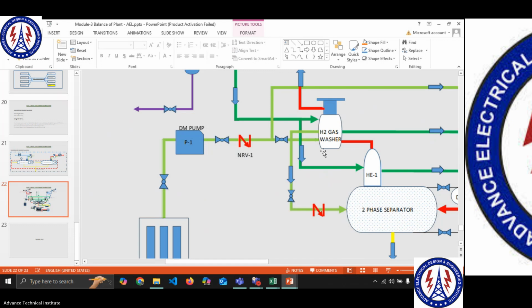Now, in 20 bar, you don't keep 20 bar. You keep 21 or 22 bar, because flow has to happen, right? If this is at 20 bar, this has to generate at least 22 bar, because some you will lose.